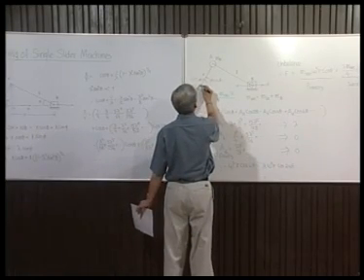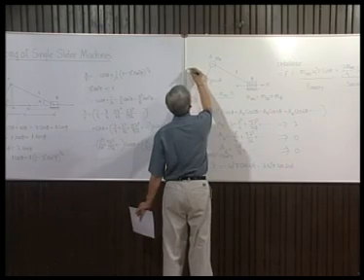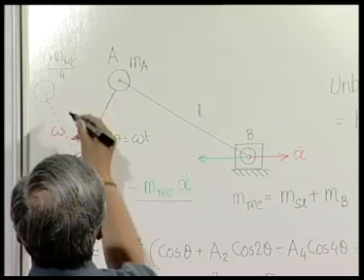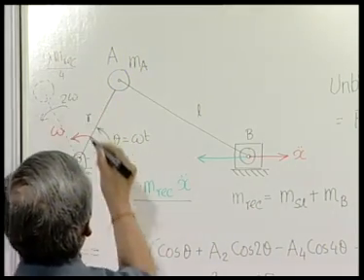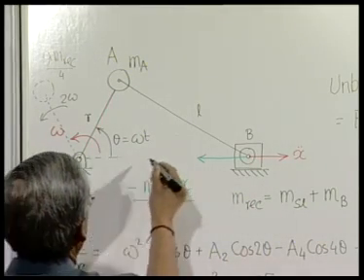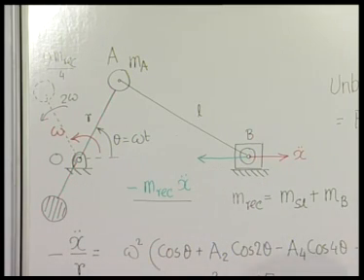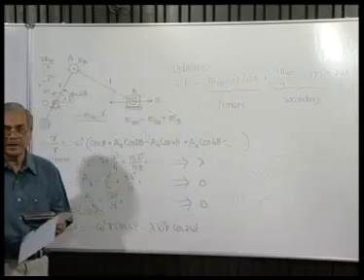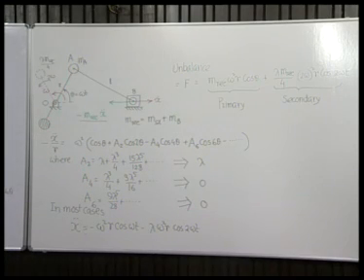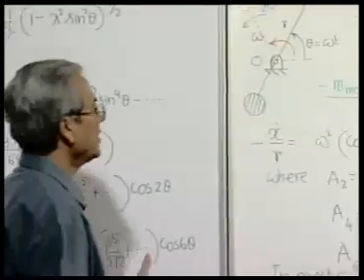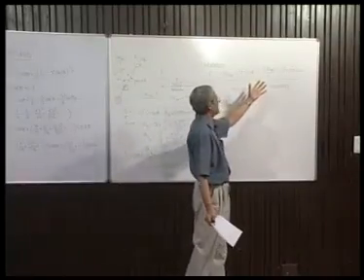Now, secondary crank will be something of the same radius but which rotates at a speed which is double the speed of the primary crank, and which was of course aligned with this at t is equal to 0. So, this angle is automatically 2 omega. Therefore, the unbalance of a single cylinder or single slider machine can be reasonably well approximated as a force along the center line, that is x direction, which consists of two components. One is the primary, other is the secondary.